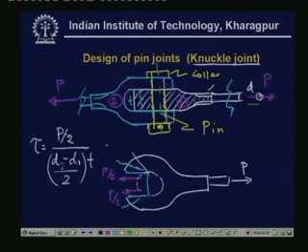So this shear stress must be less than allowable shear. So this has to be satisfied. And once this is satisfied, then it will not fail in these configurations. So this is one such failure theory. We have used again the failure theory, that this material breaks for maximum shear.